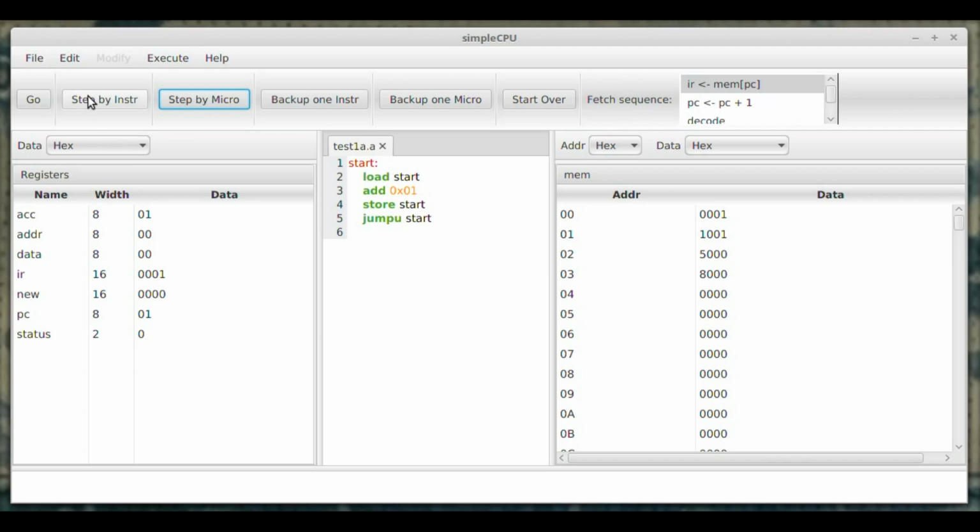Now if I step through at the machine level instruction again, have a look at what's going on at address 0. You can see that it is counting. If you go back and look at the exercise sheet, where you had that programming problem of how to reduce the number of instructions down to just 4 memory locations, this is how you do it. We can use the immediate operand field within an instruction to store data. Just to emphasize, I'm not saying that self-modifying code is a good programming technique, but it does raise questions about what is an instruction and what is data. The line blurs, so you can do some really interesting things when you start to misuse your processor.